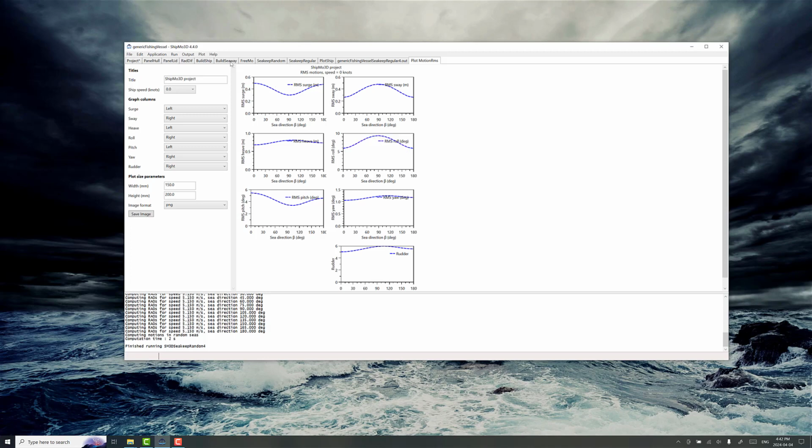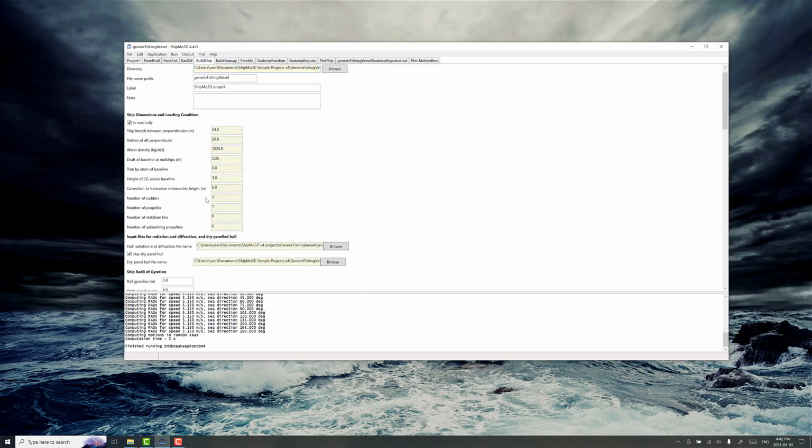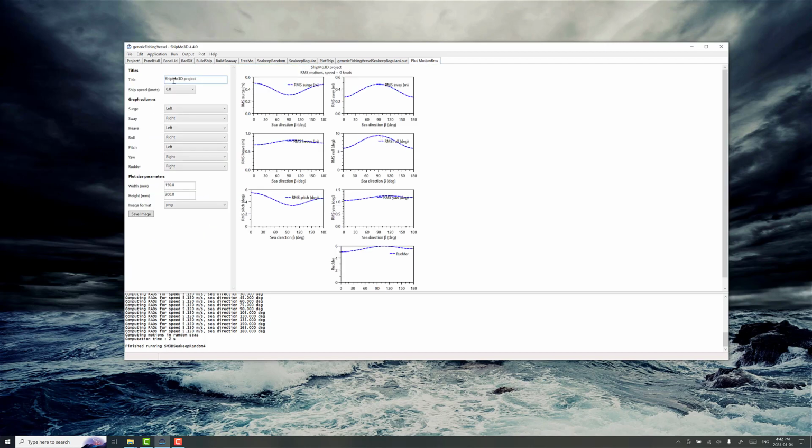Now if we go back and make a change to the bilge keels, and then evaluate how much viscous force is going up, you'll start to see trends where we doubled the bilge keel size, but it's not really significantly changing things anymore, and you can get a sense of how much value there is in adding certain kinds of hull appendages and their performance. So I wanted to highlight just those three ways of evaluating the motion control performance, particularly from appendages.